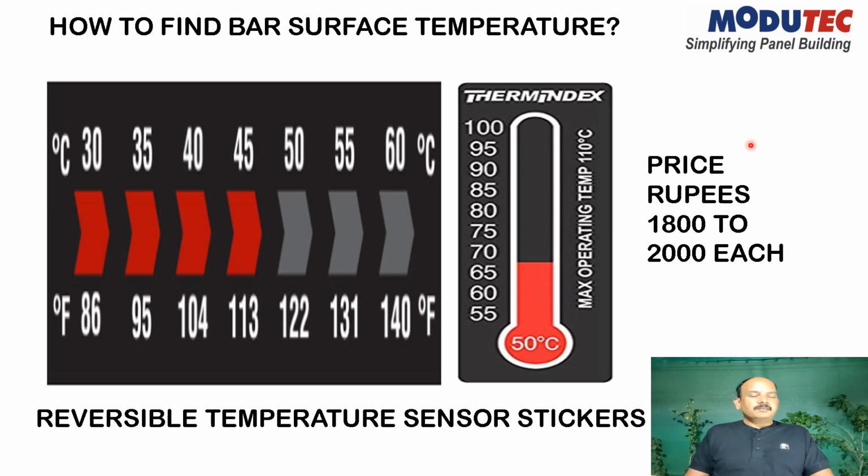How to measure the bus bar joints heating effects and all? This is one of the stickers which is available. It's a thermal based sticker. What is the feature? See, at 30 degrees Celsius on the connecting joint, this will be indicated as red. Then at 35 degrees it will go here. So both the 30 and 35 will be red. The balance will be gray color. So it will go on increasing according to the temperature available on the bus bar surface and the joint surface wherever we fix this sticker.